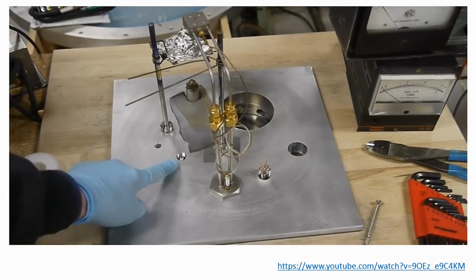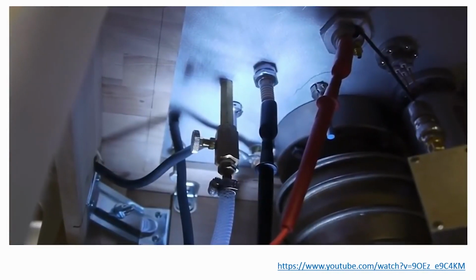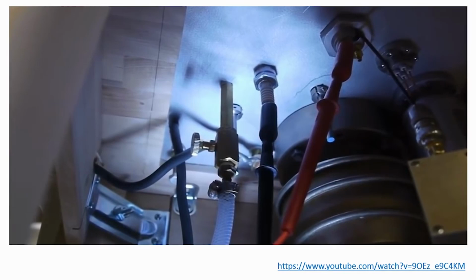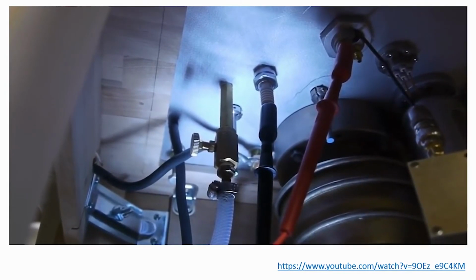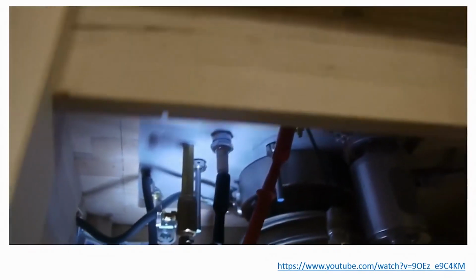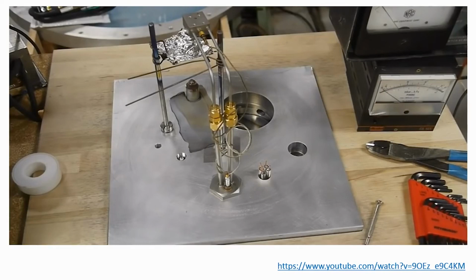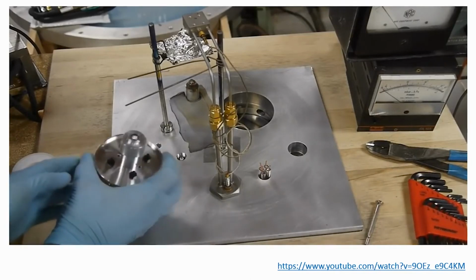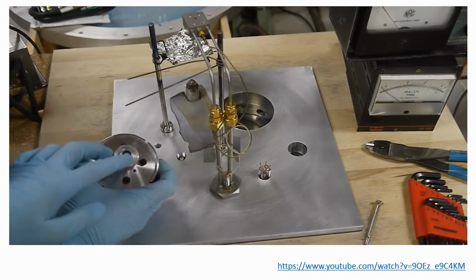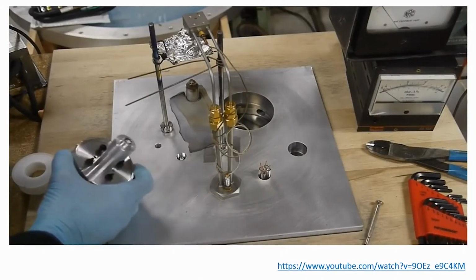And down in the hole here is a spark plug, and it's facing up towards us. So on the underside there's the rest of the spark plug, of course, and then right next to it there's a needle valve with a hose coming off, and the hose runs to my argon cylinder. So I can control how much argon is getting into the chamber through the needle valve, and I can get high voltage into the chamber through the spark plug. And the underside of the sputter gun has a rod in here that contacts the top of the spark plug, so I have sort of a shielded entry into the chamber.